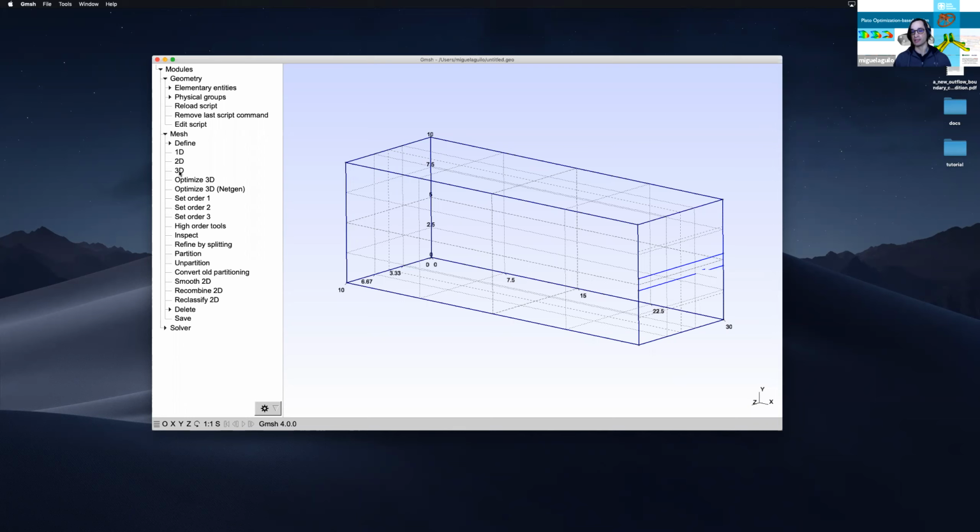So Gmsh basically takes an out-in approach to generate your mesh. First, you generate the external bounding mesh, and then you generate your internal mesh from the external information. So that's how the algorithm works.